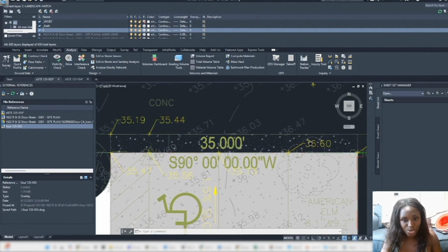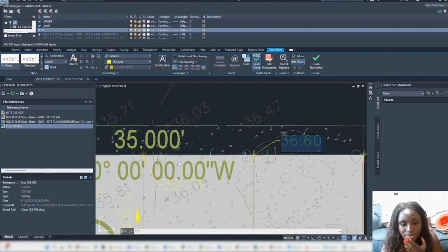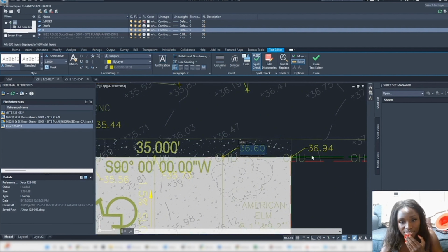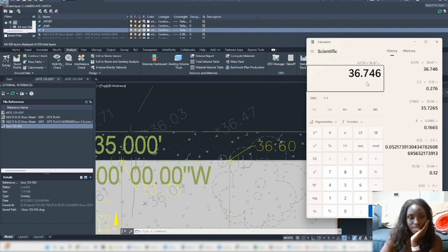And these can be more steep than that. But we're still going to be maintaining. So after we leave the ADA parking space, we can increase these to 5% increase in slope, which we may have to, so that we can do 5 to 12% in slope with these ones, because ADA has to be a more shallow drop. This is 12% that.